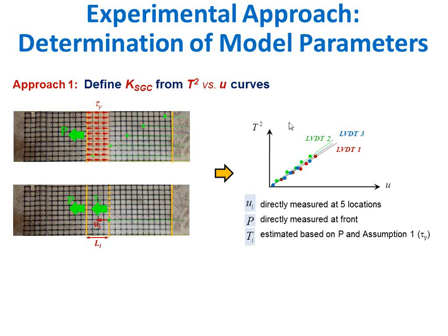Then what matters is not so much the actual value, but some correlations, or even in a mechanistic-empirical approach, what we really need is not the actual value of the property, but a good index of that property. So I cannot give you the answer to that. I would say testing that, but what you're asking is valid not only for pavements, it's valid for reinforcements in general. There are some studies that would argue the following.